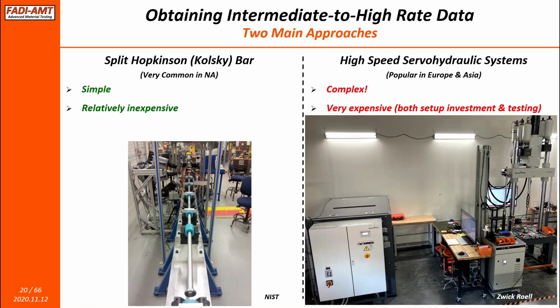So this broader picture that I'm showing of the entire system, to some extent, because it's a servo-hydraulic machine, of course, you need a hydraulic pump, and because of that, you need that chiller, which is usually outside. So that's basically an additional component, and you have the load frame itself that you can see on the far right. The load frame, as I mentioned, is a high-speed servo-hydraulic system, so that's why you see all these accumulators on the top to allow it to go to high speeds.